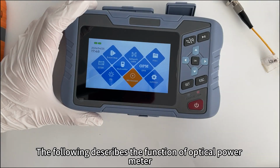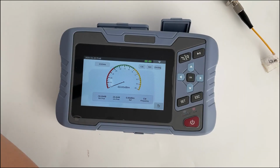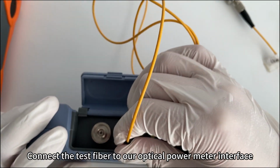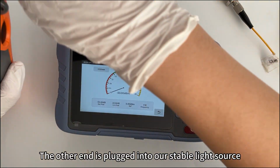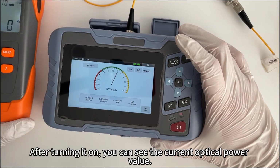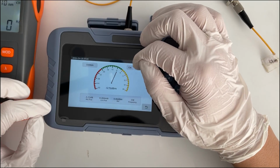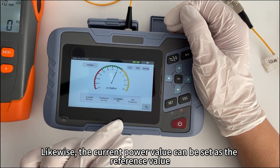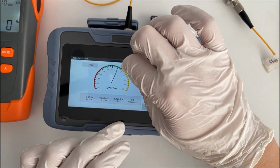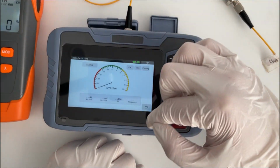The following describes the function of the optical power meter. Same as before, connect the test fiber to our optical power meter interface. The other end is plugged into our stable light source. After turning it on, you can see the current optical power value. Likewise, the current power value can be set as the reference value. Click Calibration to calibrate the power value.